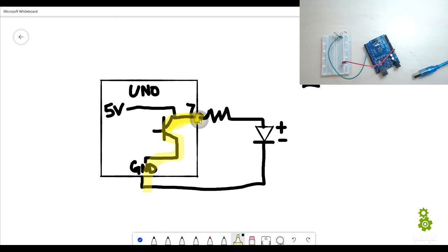And then what happens? Do you have a loop still? You have a loop here, here, here. So you still have a loop, but now you only have a GND connection. So there's only GND, there's no 5V. So it's just going to be 0 volts, no power. Okay, so even though you have this closed circuit, there's no 5V in there, so you're not going to get power. And so when you go low, it's going to be off.